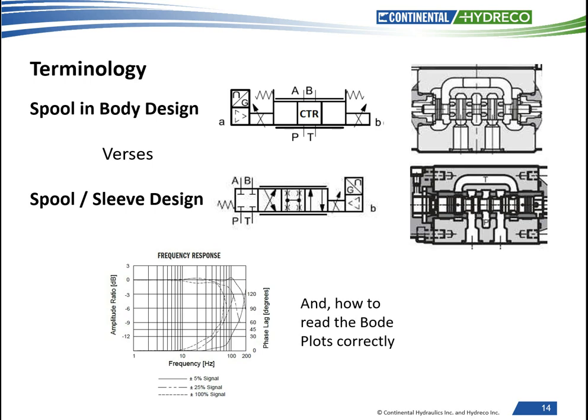Phase lags are additive. In a hydraulic control system, there are many things that will cause phase lag: response times of various components, compressibility of fluids and lines, mechanical stiffness, backlash. In a typical cylinder positioning system, our hydraulics and mechanical add up to about 90 degrees of phase lag. So when we try to run a valve at its 90-degree point, well, I think the motion controller may have a hard time becoming stable.